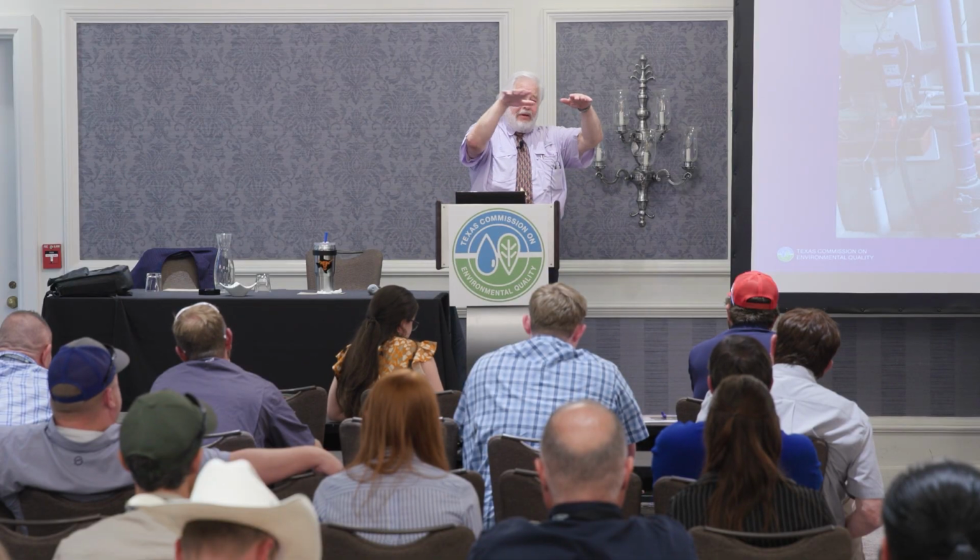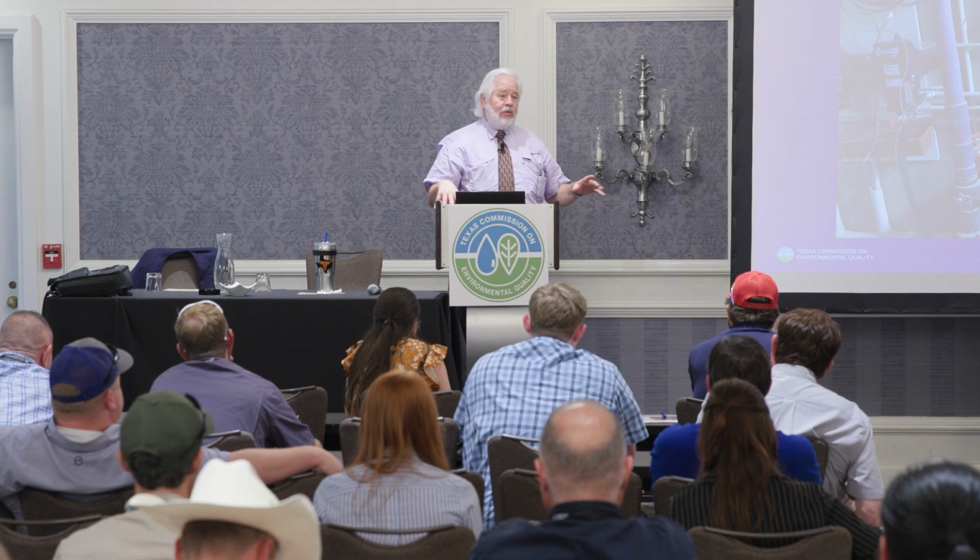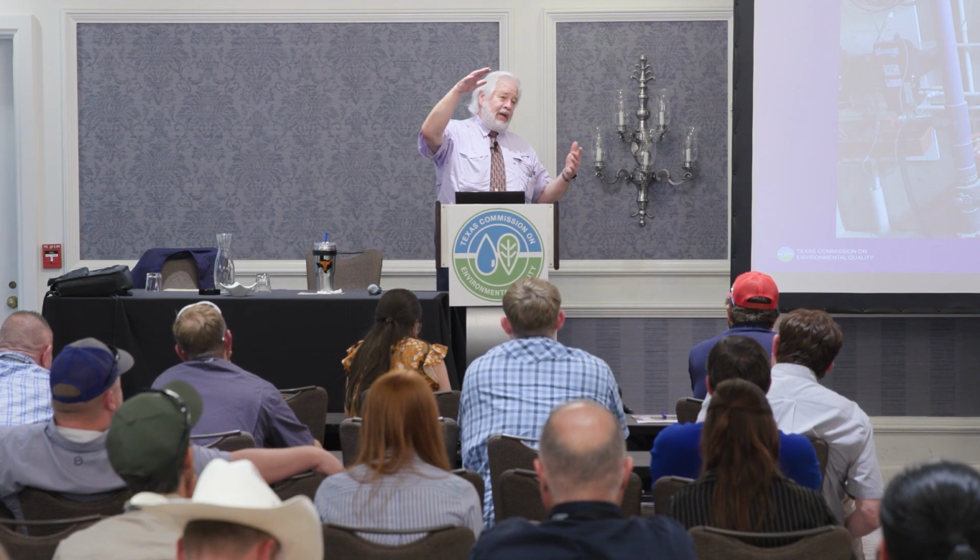So you can backwash on whatever criteria you want. I usually say, operators I know talk to me about head losses around 4.5 to 6 feet, IFE turbidity levels about 0.3 to 0.4, and filter run times of 120 to 140 hours, okay? That's like 5 days of continuous running before I have to backwash the filter.